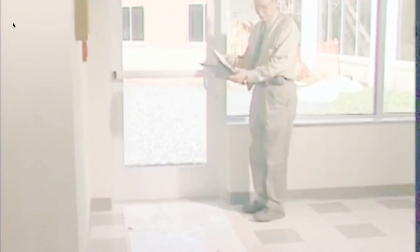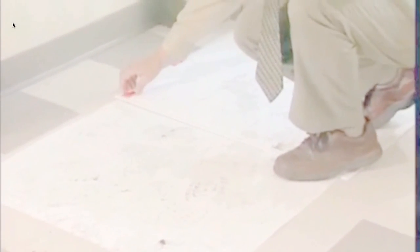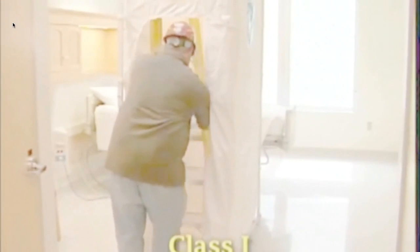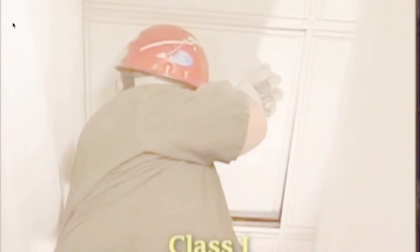The ICRA also identifies the accountability of individuals during implementation. The ICRA should establish the frequency and type of documentation prior to the start of the project, even on work orders for routine repair and maintenance tasks. For a project labeled Class 1, the key is to minimize the raising of dust and keep the area clean. Doors should be kept closed to the work area and ceiling tiles replaced immediately after visual inspection.